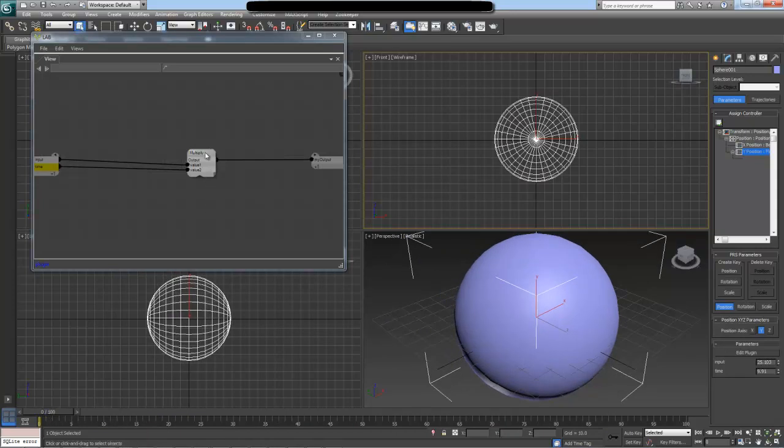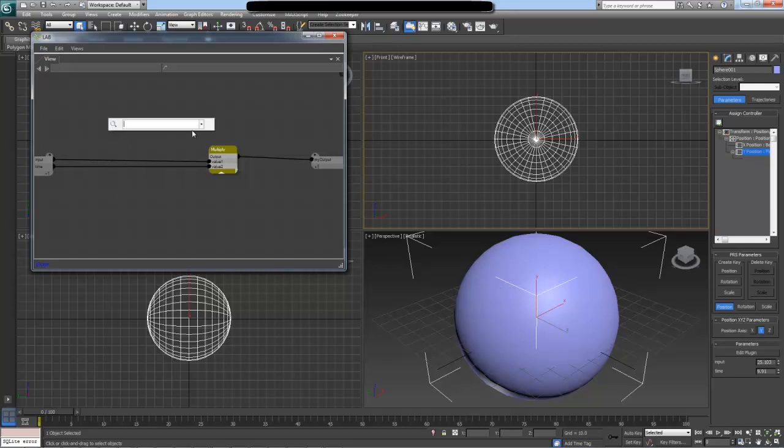As a last note, let's also make it more interesting by making the sphere go back and forth in the viewport. And to do that, let's add a sine node. A sine node is a basic mathematical operation, a trigonometric operation, which allows you to have objects move in a circular or sinusoid motion. And inside the lab, we use the default .NET sine function, which is system.math.